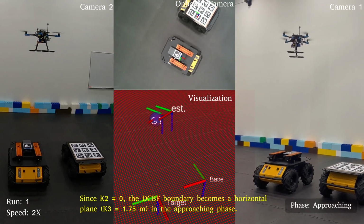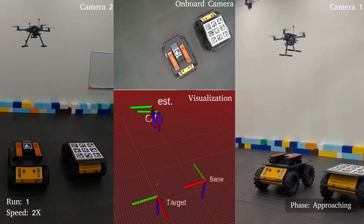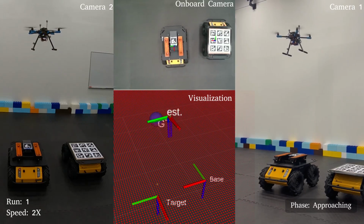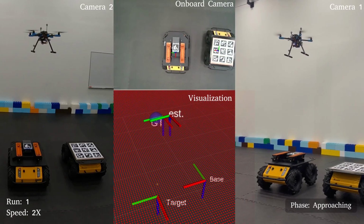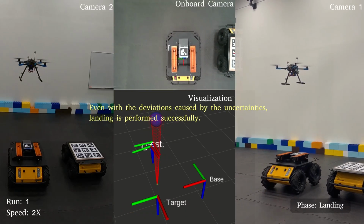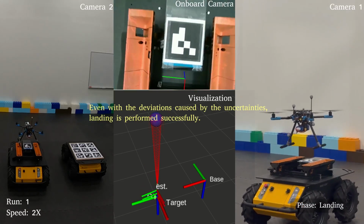Even in this case, K2 becomes 0 as the target is detected at an altitude below K3. Hence, the DCBF boundary becomes a flat plane in the approaching phase. When the controller switches to the landing phase, the DCBF is modified with the parameters obtained from the altitude of the landing region B and the relative position of the UAV at the time of switching. This ensures the vertical descent of the UAV in the landing phase.